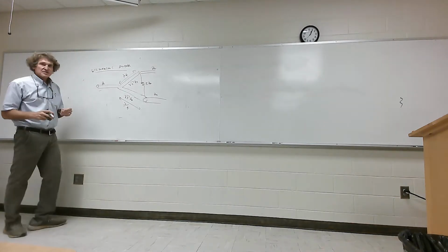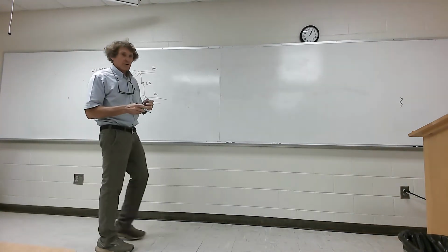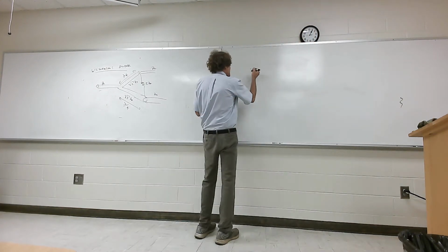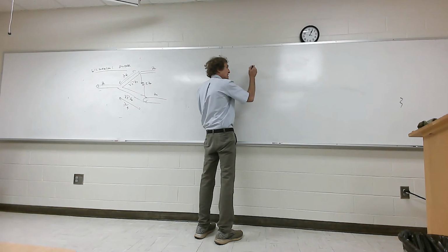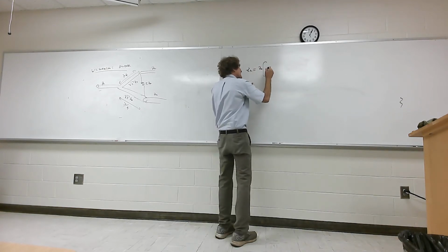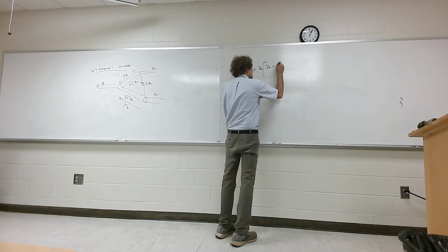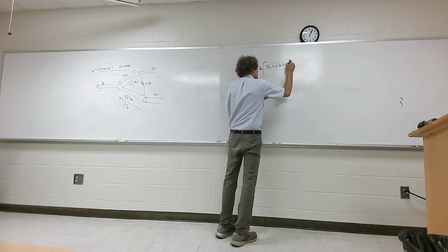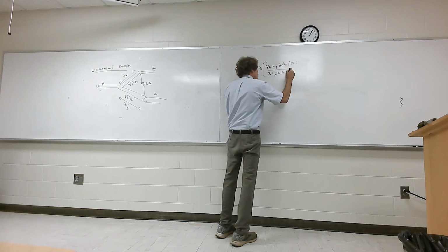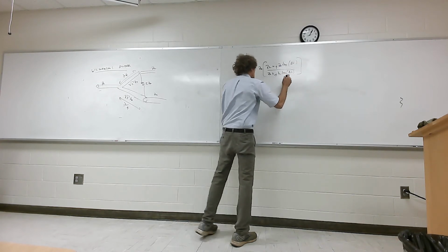So when you have this, what do we know about a quarter wave transformer? And I want to make sure I bring this out. When you had a quarter wave transformer, you remember if I had something and it was a quarter wavelength, let me do it this way. So I knew that Zin for anything was Z naught times Z load plus j Z naught tangent of beta L, over Z naught plus j Z load tangent of beta L. That was the input impedance.